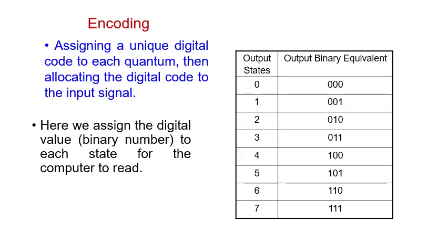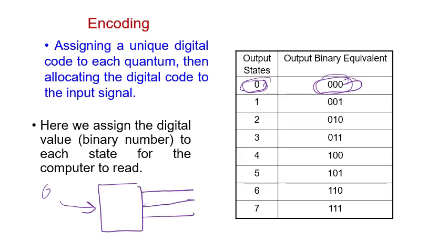Okay, now the encoding. He's saying it's very simple. Each set having a certain analog value will be matched by a digital value. So 0 digitally means 000. If we get 0 at the input here, on the output, in this 3-bit system, we are going to get 0, 0, 0. What about the second set? Remember in the previous slide, it's 1.25 to 2.5.